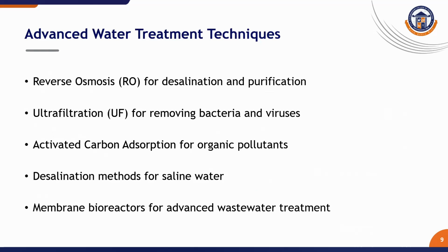Advanced treatment techniques. The reverse osmosis pushes water through a semi-permeable membrane to remove salts, metals, and even very small organic molecules. It's especially used for the desalination. Ultrafiltration uses finer membranes than sand filters and can remove viruses and bacteria. Activated carbon absorption is used to tackle taste, odor, and organic chemical pollutants. Membrane bioreactors combine biological treatment with membrane filtration to treat wastewater to very high standards, making it suitable for reuse. These technologies are critical in urban areas, industries, and water scarce regions.